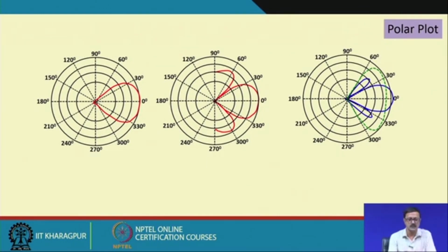On the left side, this is a single polar plot, where this particular loudspeaker has this kind of directivity, and this is the equal SPL contour. This is maybe 2 or 3 microphones, or maybe a single microphone has this kind of a little bit complex directivity, where these are the polar plots of that particular loudspeaker.